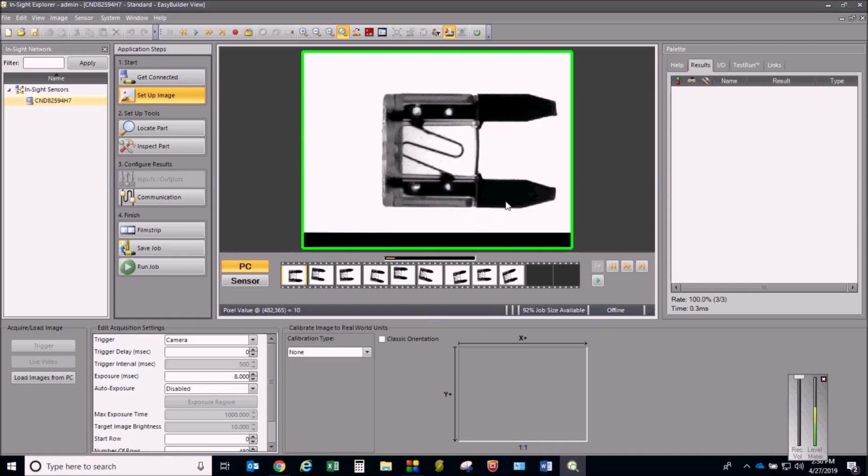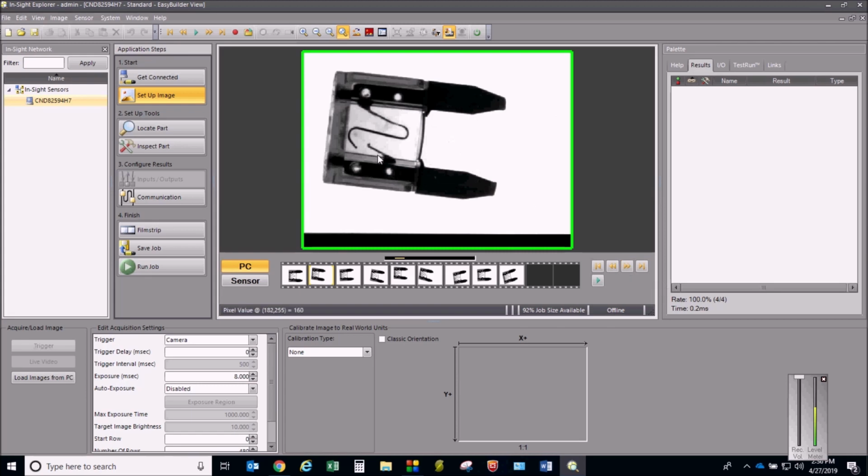The way this fuse works is any current for this circuit is going to go into this spade lug here. It's going to flow through this filament and then out to the other spade lug. It's basically a switch. It's basically a thermal switch. And what happens is if too much current flows through this filament, the filament will heat up and it will burn out, and it will look like this is what will happen. So they've sized this filament in such a particular way that a 15 amp fuse will allow 15 amps of current to flow.